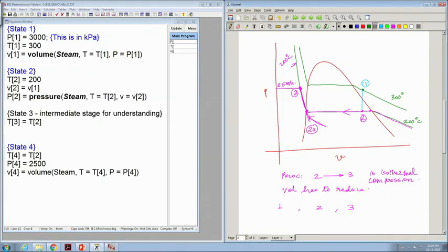What is the other property that we can use over here? If you said it's the quality, you are correct, because we have already seen that in the saturated dome, it is the quality and some other property that we can use to quantify. So, x equal to 0 is a point on the left limb of the saturated dome.